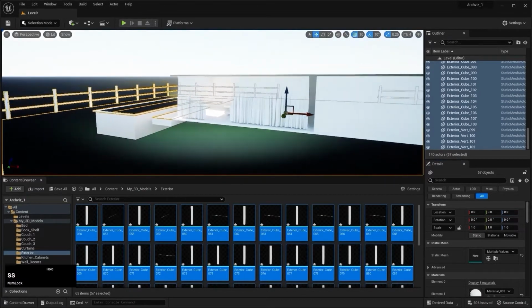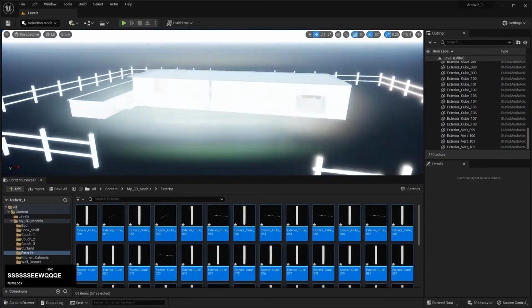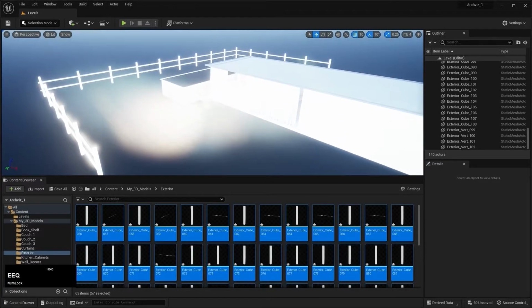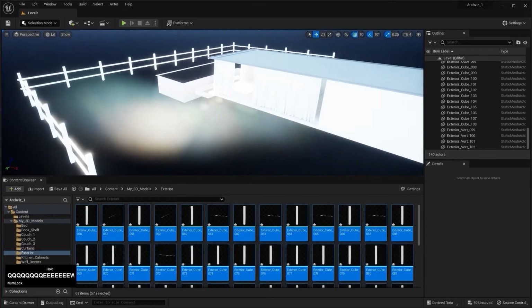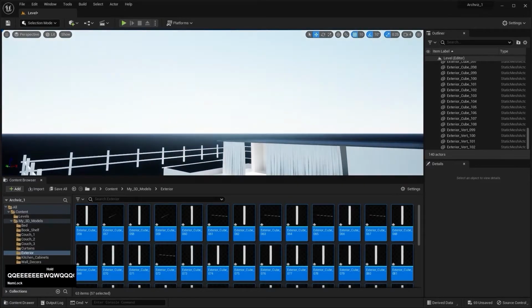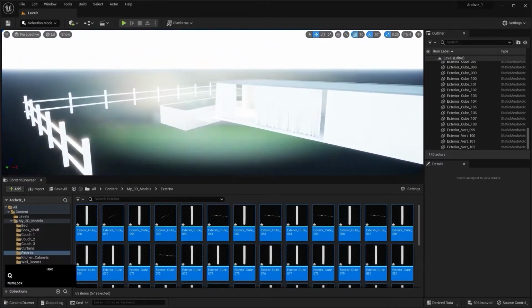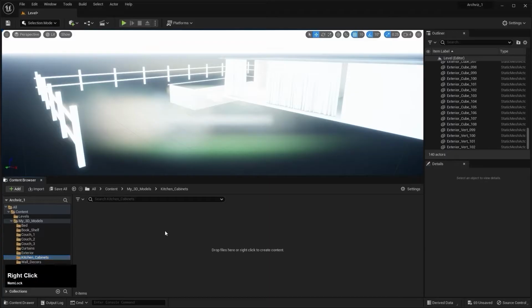Now this is something strange because we did model a surface inside this fence in Blender. The reason we can't see our surface is because we need to go back in Blender and recalculate the normals for this surface. We'll deal with that later. For now, just import our collections.